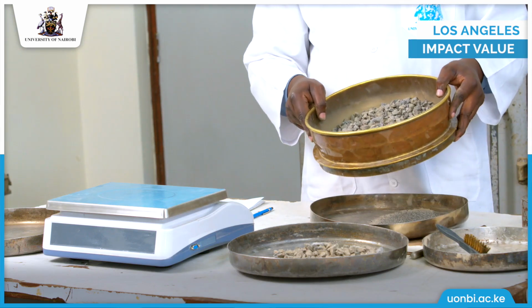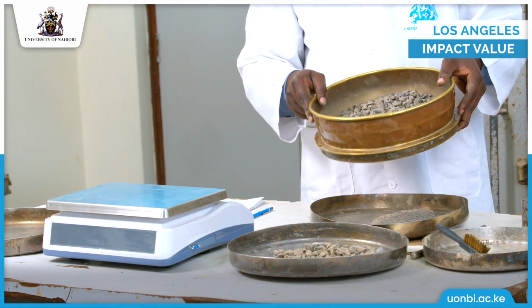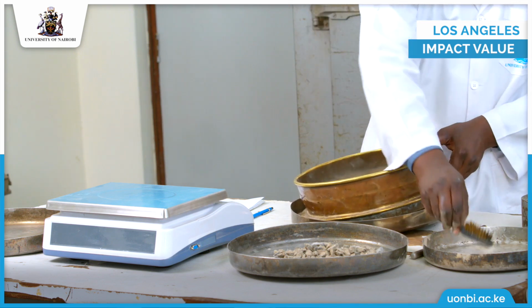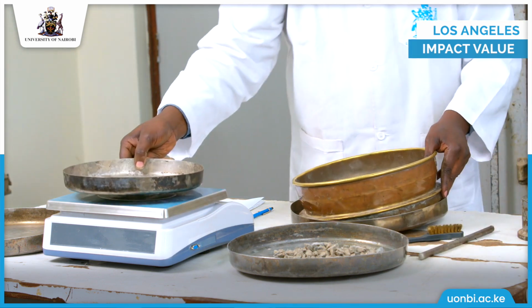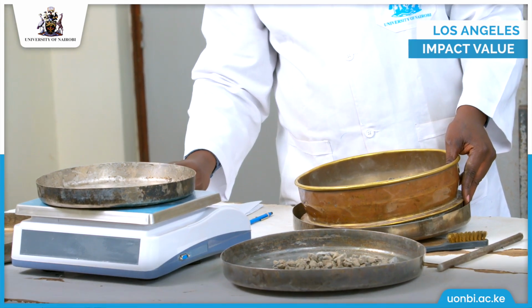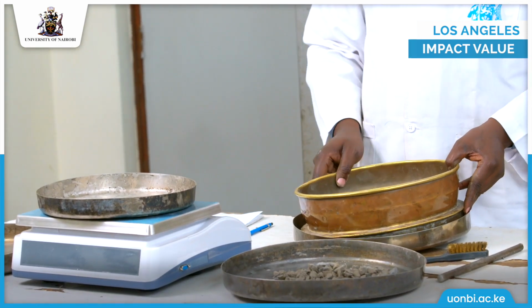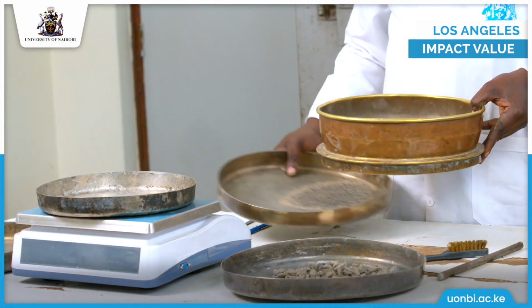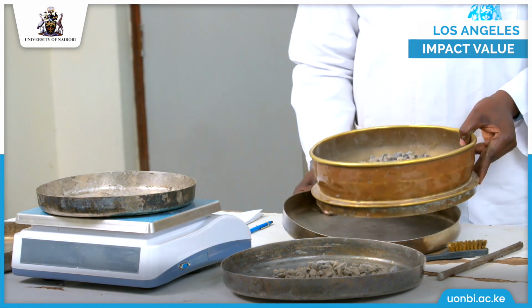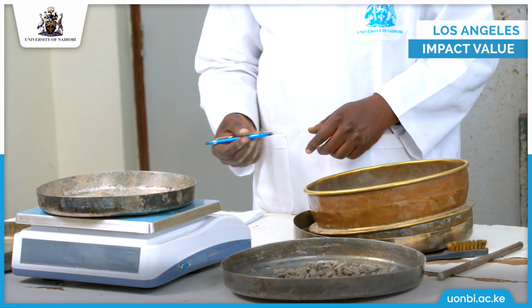So here we have the weight that has been retained, also the larger size. And we have the smaller size that is passing. We're expected to get the weight of the passing. So using our weighing balance, I can tare the weight of the pan so that we have 0, so that I measure the weight passing. In this case, the weight passing is 50.9 grams.